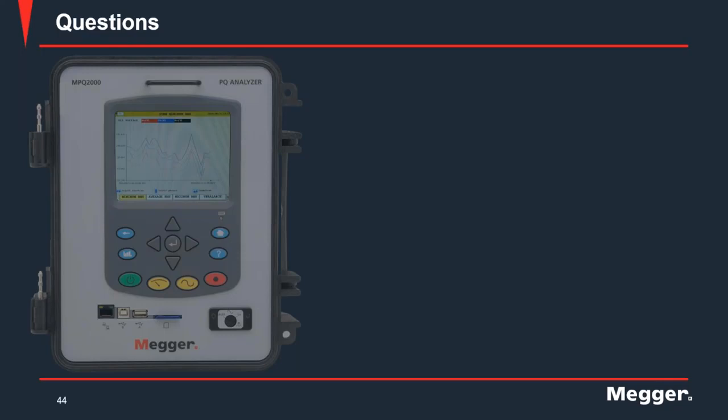Okay. I pretty much think that what this question is really asking is, is it a good practice to go and use a DC lighting system such as an LED system? And really there's pros and cons to pretty much everything in the world. But when we go to an LED lighting system, which is run off DC, yeah, it's going to be a lot less prone to flicker and RVC, rapid voltage change, depending on the design of the rectifier in it. So in general, they're going to be less prone to that, so you should see less flickering. And they do have a longer life, and they do use a lot less energy.